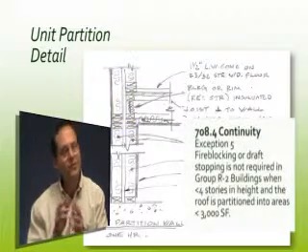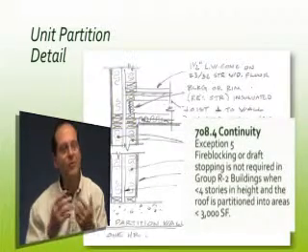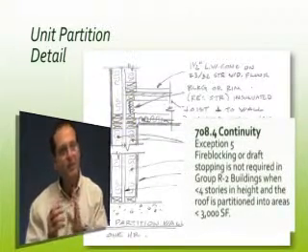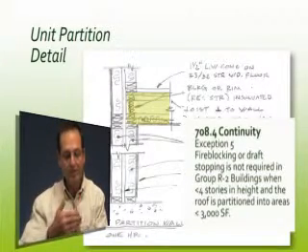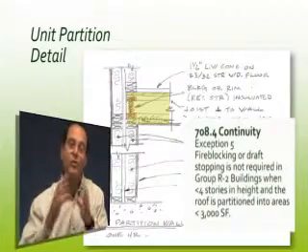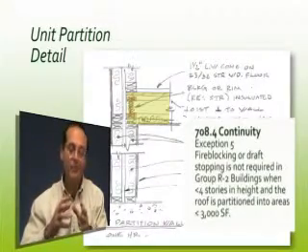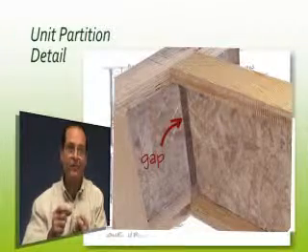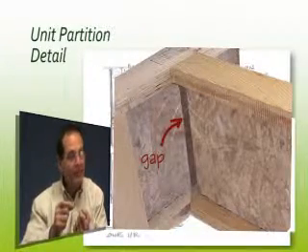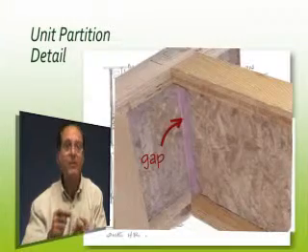There is a provision, 708.4, that has to do with continuity. At that spot where the blocking panel is, you've got a joist bearing on top of the wall, you've got a blocking panel in between it. When you put those two together, when they're wooden I-beams, you end up with a gap, right? Well, is that gap legal or is that not legal? Should that be stuffed with insulation?